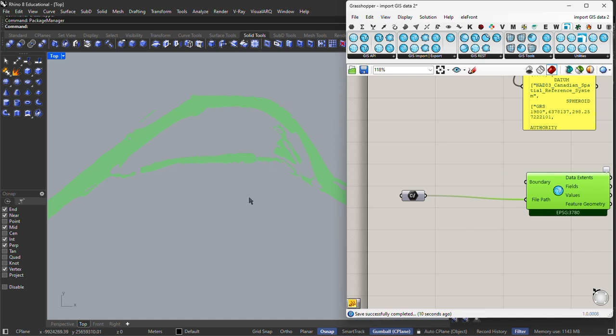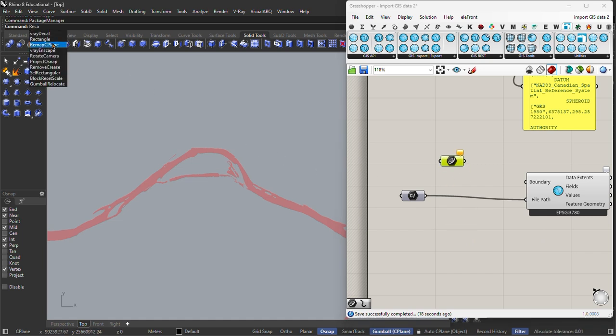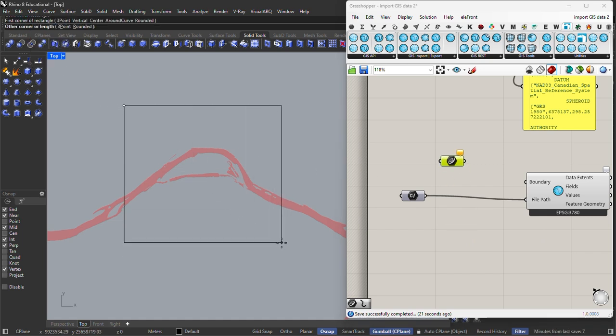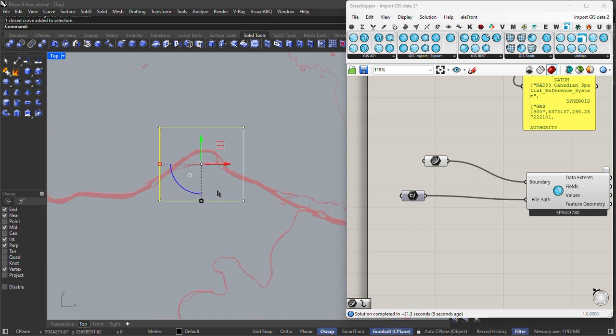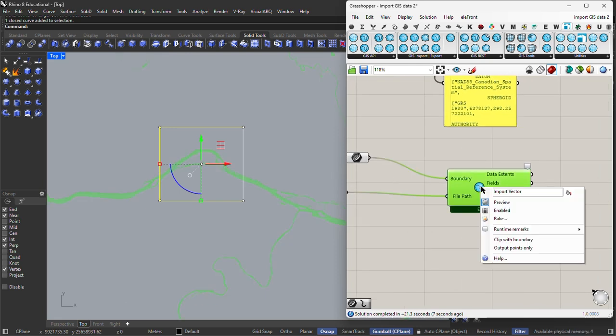Let's do downtown now. We create a curve component and reference a rectangle here, a small one. Make it as small as possible, just focus on your area, and reference it here. Set one curve and I will internalize it in this script, save it and then plug it into the boundary. And now only the geospatial features within this rectangle will be plotted. Once this is out, I forgot to clip to the boundary.